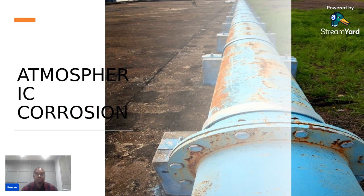This type of external corrosion is a form of oxygen corrosion. It occurs where the surface is continuously wetted with aerated water. So what that means, just to explain a bit more, is where you have continuous rainfall, which is water, obviously, falls on a metal surface, and with oxygen being all around us.